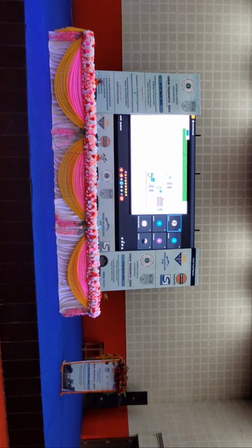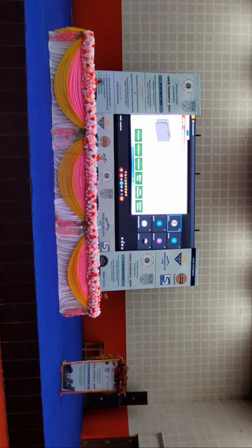Just a comparison for scaling up: if you want to scale up energy or power independently, in the case of a traditional battery, you have to add more batteries. If you add them in parallel, the voltage is the same and the capacity increases. If you add them in series, the capacity is the same and the voltage increases. Whereas in this flow battery, the vanadium flow battery, if you want to increase the power, now you see the power is increased. If you want to increase the energy, now you see the energy is increased. That is the meaning of decoupling energy and power.